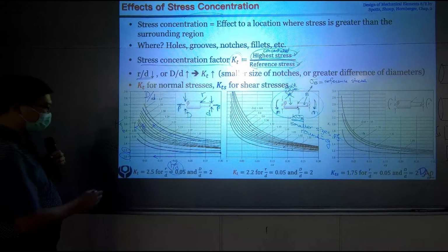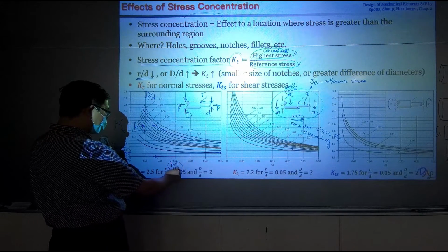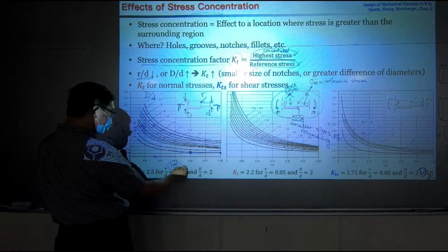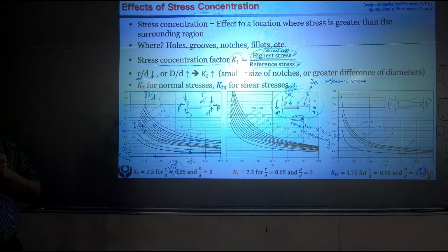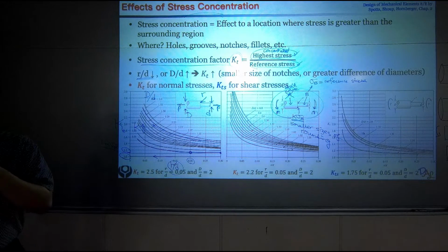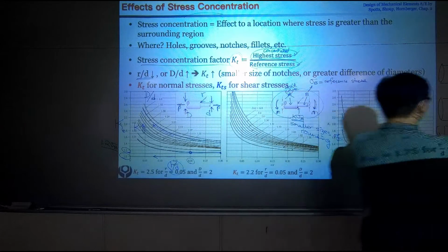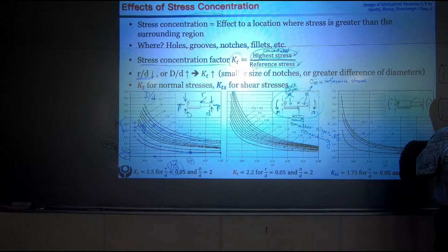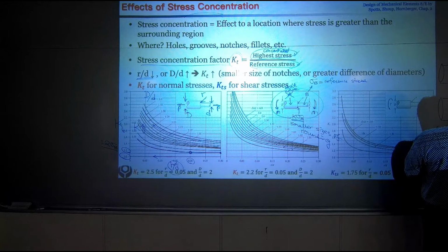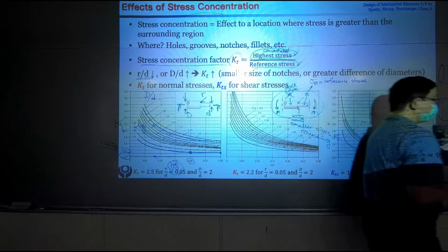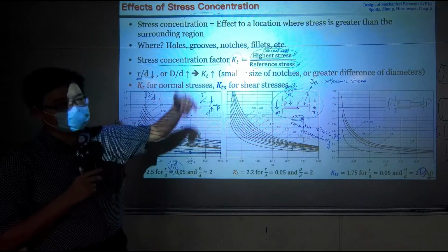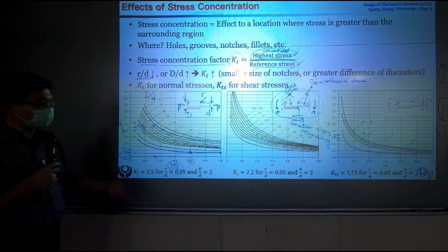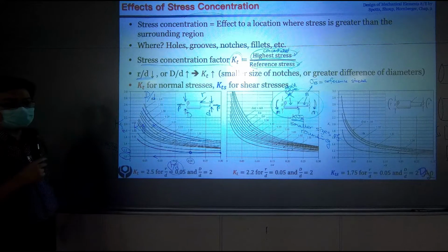So in that case, I probably need a ratio of something right here, 0.2. So your radius needs to be as large as 20% of your diameter. When you're designing, this is your small d, you need to make a rounding having a radius of 0.2 d.